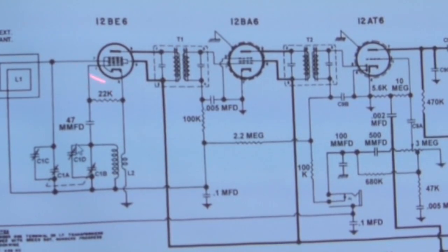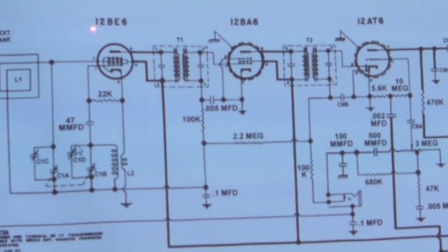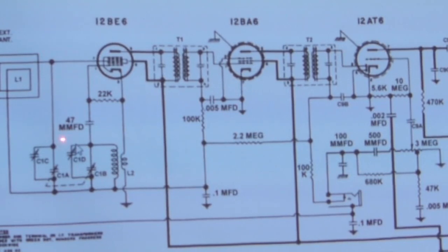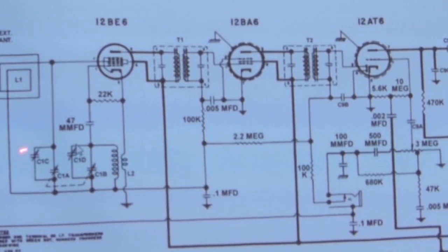The heterodyning operation in the mixer oscillator takes place because when two signals are combined in a nonlinear environment, they mix together in a heterodyning effect that produces the sum and difference frequencies. In an audio circuit where you have mixing, and everybody knows about an audio mixer, you have two linear analog signals coming in to a linear environment, so they don't heterodyne together. And that's the difference between a radio heterodyning and an audio mixer. It's an important difference. When we get into audio circuits later, we'll talk about that.